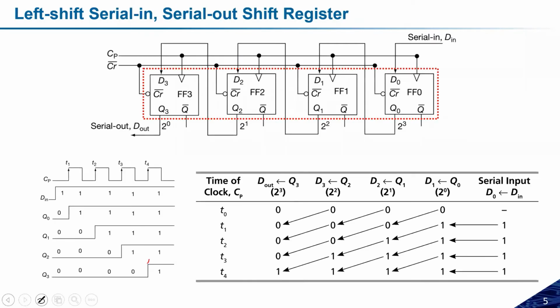Similarly, let us try to change the logic. I want to make the same kind of register, a serial input serial output left shift register, but with asynchronous loading. What is the meaning of asynchronous loading? Let us go back to the previous slide. In this slide, whatever data we have loaded here will move in the left direction, and we are not clearing anything.